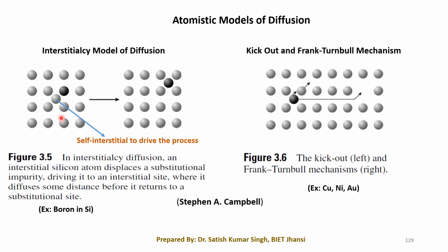In the silicon crystal lattice, what we can find is a host atom sitting in a particular interstitial site, whenever a dopant, any impurity atom, has already occupied a particular substitutional site. This silicon atom sitting in an interstitial space is actually called the self interstitial.